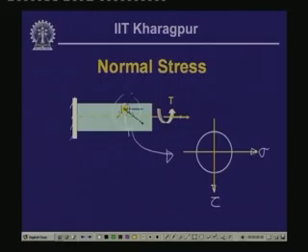Here, as we have designated earlier, the shearing stress acting on this element, according to our convention, is negative, as this shear along with the complementary shear is making a moment in the clockwise direction, which is negative. So, on this axis it is represented by this point, whereas the shear on the other plane is positive, which is making a counterclockwise moment. This is represented by this point.